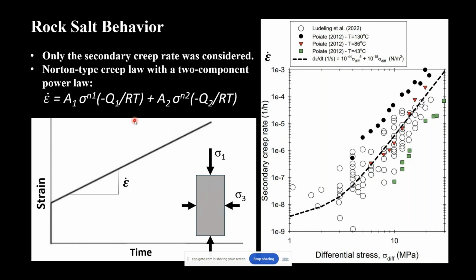And here, because the height of the salt caverns is not that big, the change in temperature from the top to the bottom of the cavern is not that important. So we can assume that the temperature is constant. So this term here becomes a constant, basically. And this is the response of the model if we simulate a triaxial creep test.